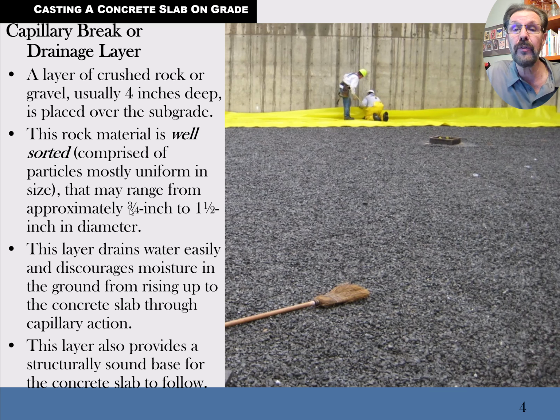But in this picture here, you can see a basement wall back over there in the background. So that basement wall is sitting on a foundation. So in those cases, even then, the slab on grade inside of a building like this is just 4 inches thick. It's not thickened at the edge. If anything, it's a floating slab.